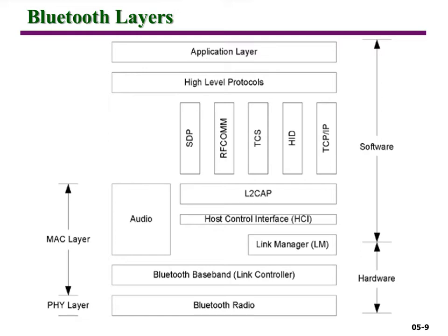Okay? So to set up a new connection, you need to call some APIs from this layer. While you are setting up the connection, you need to define whether this is for voice or for data communication. Whether you need to pre-allocate the time slots from the beginning, or you don't have to establish any connection, in which case there is no actual connection context in the link manager for this particular connection. Or you can stop the communication or tear down the connection at any point in time.